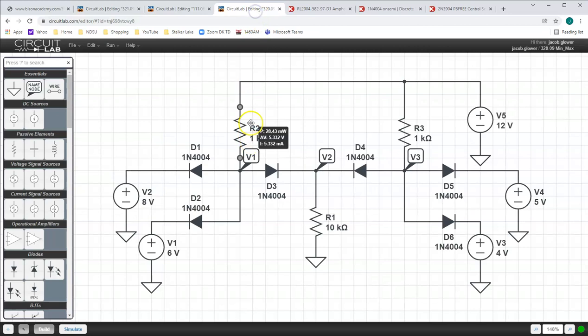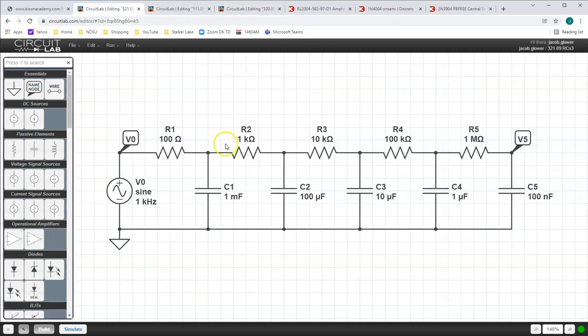If I have AC components, here we are, I can use the phasor representation. The capacitor becomes a complex number, 1 over j omega c. The voltage source becomes a complex number. The real part's cosine, minus j is sine. Set up n equations, n unknowns, and solve. Only now I'm using complex numbers. So again, that's something that you're familiar with for linear circuits.